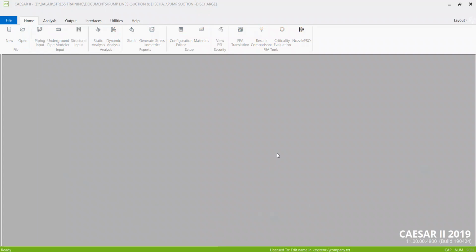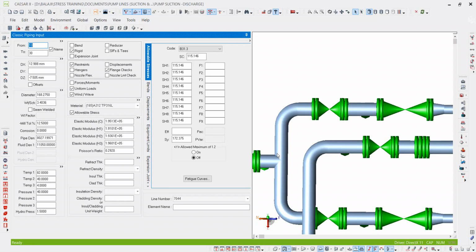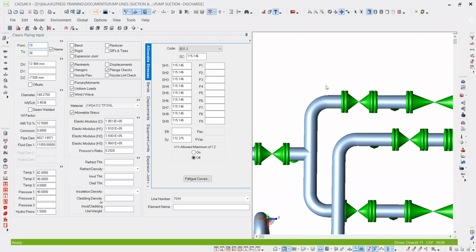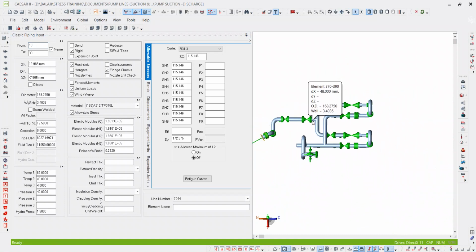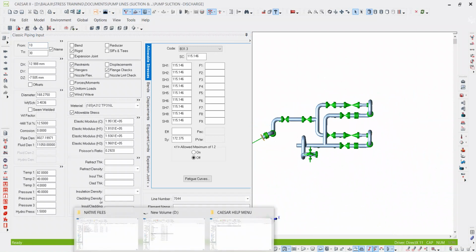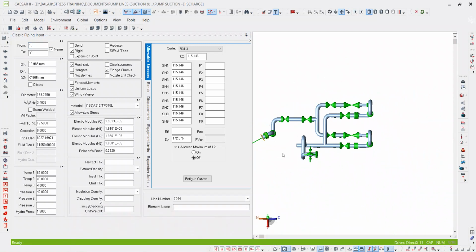Mainly in hydro, occasional and sustain, supports are very important. So you need to add support as per the span. But in the pipe support center, the span is provided only for straight pipes. If any valves, strainers or other rigid elements are coming in between, then that span is not applicable. So you need to provide the support as per your experience or as per guidance from your lead engineer.